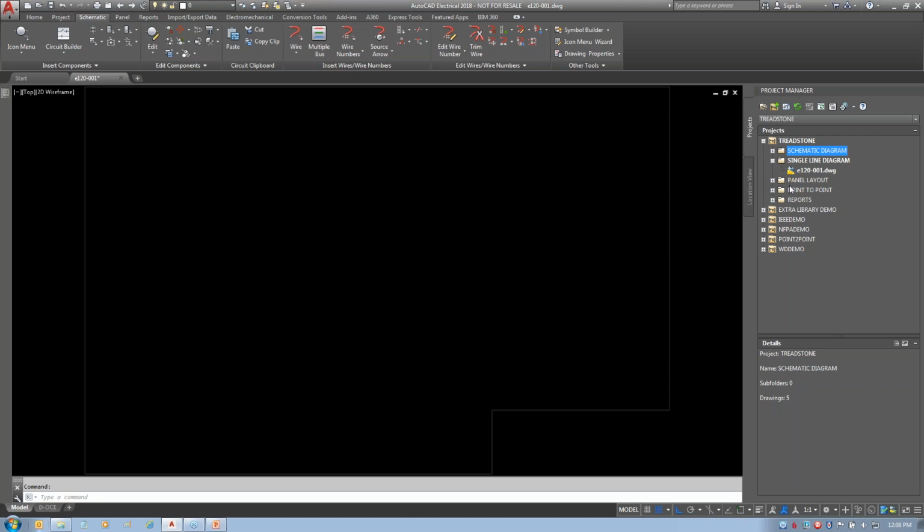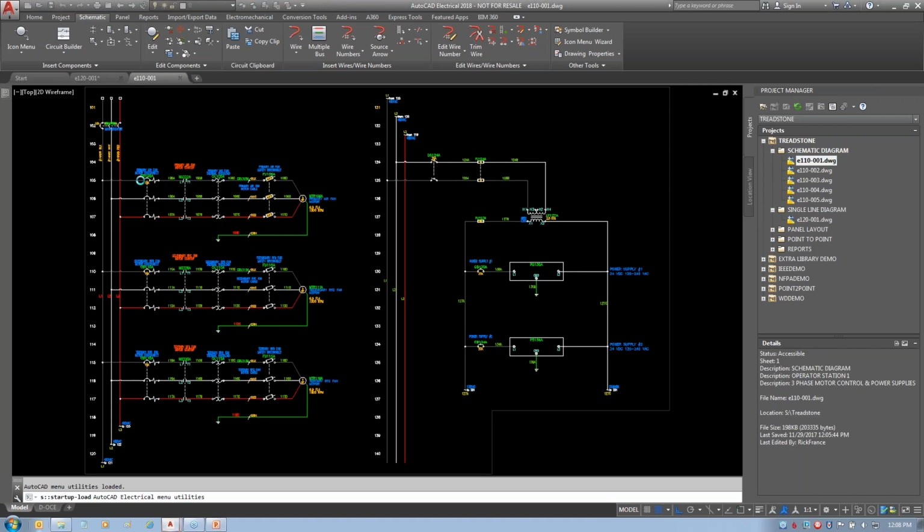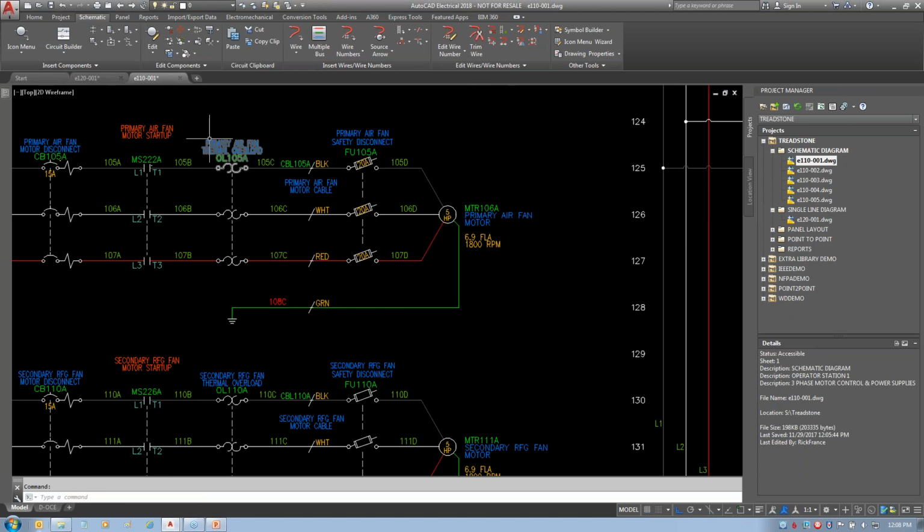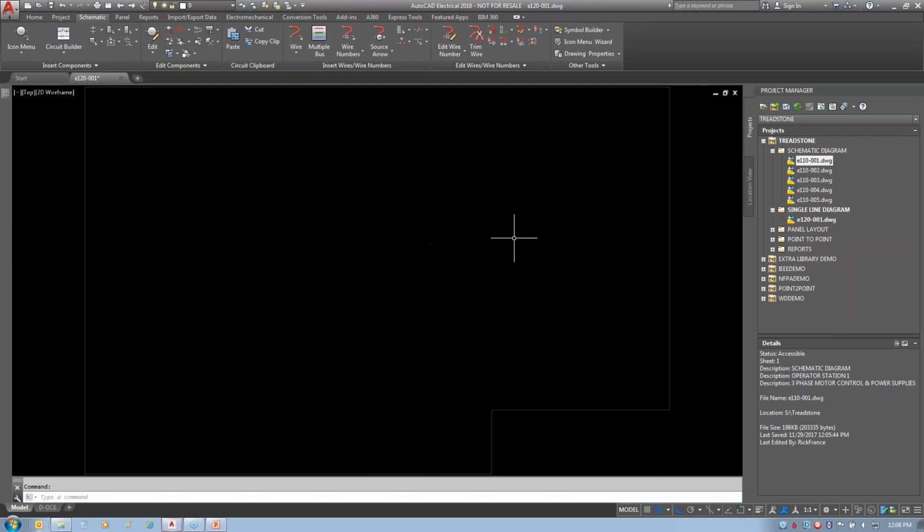because there's two ways I could get a ladder. I could start out with my wire diagram here. One is I could use just a regular ladder. Now, if I was not going to be doing my single line diagrams, connecting them up to where it's using the same exact circuit here and the same exact overload here, if I wasn't going to make them the same one with the same numbers, then I probably would want to put in a ladder. And some people do it this way. Also, for instance, I've been at companies before where we didn't do ladder diagrams. We did just single line diagrams.